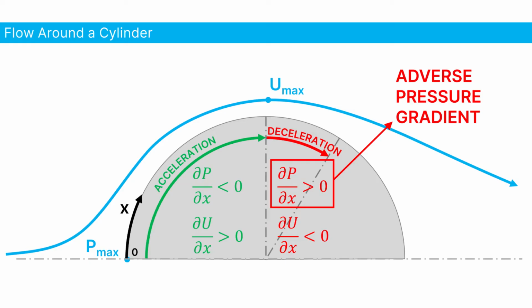Now, as the pressure drops with increasing distance traveled x, we can talk about a negative pressure gradient, which is good. The airstream is actually being pushed forward by the pressure delta, and this helps to overcome the friction generated in the boundary layer, which gradually grows thicker.